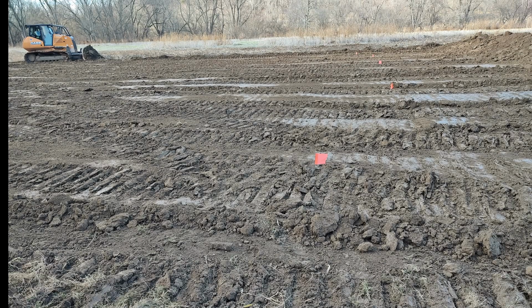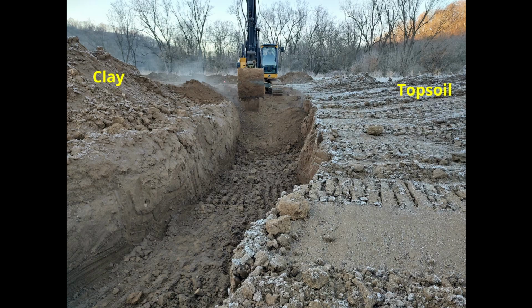Orange wire flags are placed in the ground to show the excavator operator the center location of the groundwater dam we're going to build. The excavator operator begins by digging a trench for a groundwater dam. The trench is dug below the depth of any crayfish burrows that are present. Topsoil and organic material that are removed are placed on the right side of the trench. The soil that's high in clay is placed on the left side of the trench. We'll place this clay back in the trench to form the groundwater dam.